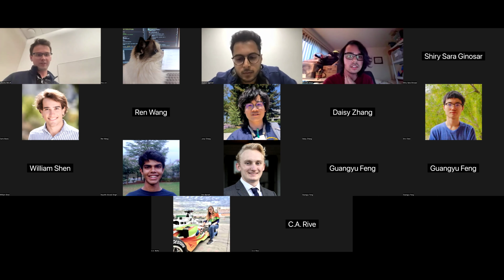I agree with you that human hands would not be able to move your finger in this position. I would say that's a limitation of a human hand, and it's still desirable to have robot hands which can do that. The reason we built this in the first place is that the first iteration of the hand did not have this capability. We tried training a policy to rotate very small objects, like a ball here, and it turns out that's really hard if the object is oblong, because you need the hand to be able to move the finger around the object. So this particular movement is very useful if you want to do fingertip manipulation.